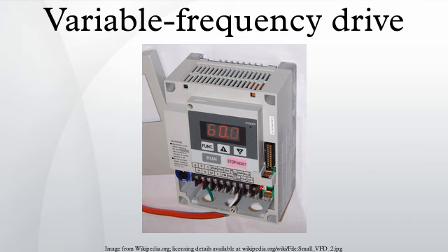Operation of the motors above rated nameplate speed is possible, but is limited to conditions that do not require more power than the nameplate rating of the motor. This is sometimes called field weakening, and, for AC motors, means operating at less than rated volt per hertz and above rated nameplate speed. Permanent magnet synchronous motors have quite limited field weakening speed range due to the constant magnet flux linkage. Wound rotor synchronous motors and induction motors have much wider speed range.